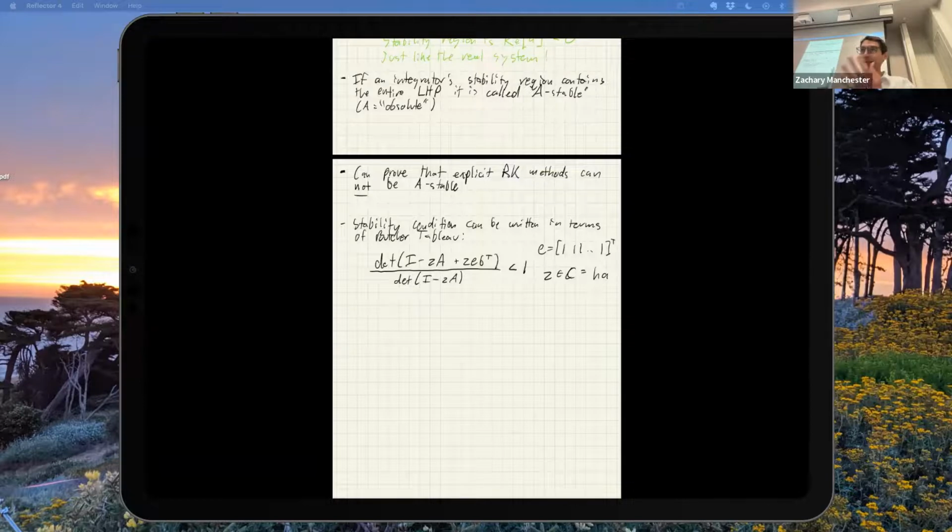So what you can do then is start thinking about Lyapunov ideas. You can write the discrete time Lyapunov stuff, and you can write the continuous time Lyapunov stuff. So what you could basically do is, if you had a nice Lyapunov function for the continuous system, you could write it down in continuous time and then plug it into the integrator and check the same Lyapunov function in discrete time on the discretized system, and see if they give you the same stability properties. But basically, as with many things in life, nonlinear stuff is hard, and linear stuff is the stuff we know how to solve. So you can get really far with linear stuff for stability analysis, and we generally use it, and it's pretty powerful.